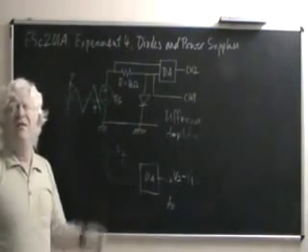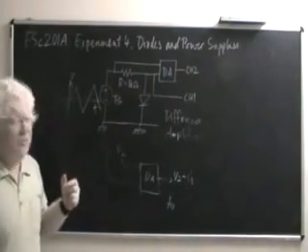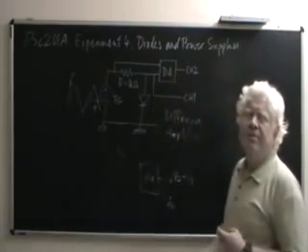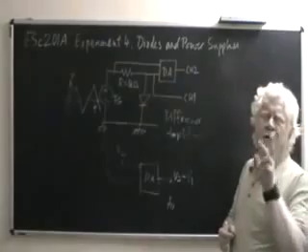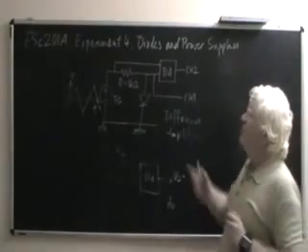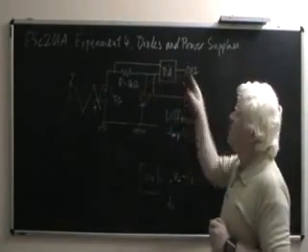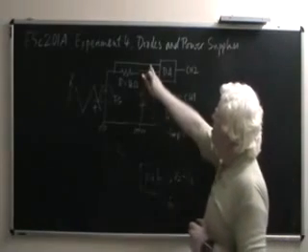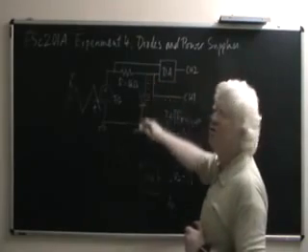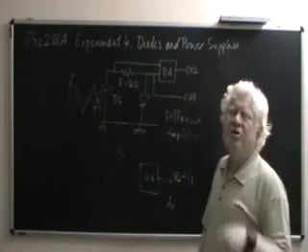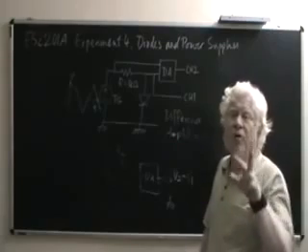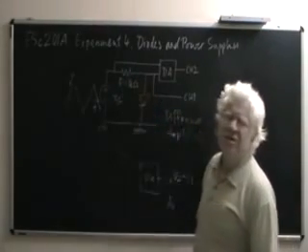This is the task that needs to be done, because for either channel of the oscilloscope, one end of the two terminals of that channel is already grounded. So if we take these two wires and connect them to one channel of the oscilloscope, for example, if I connect this and this, then the oscilloscope will itself ground this point. So there would be no voltage across the diode at all. Hence, an oscilloscope can measure only voltages with respect to ground. It cannot measure a floating voltage, which is what you will find across this resistor.